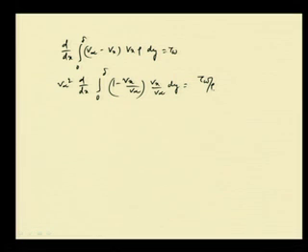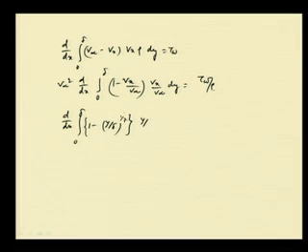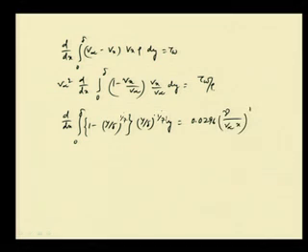Now we put that expression for Vx by V infinity, and we get d dx of the integral from 0 to delta of (1 minus y by delta whole to the power 1 by 7) into (y by delta whole to the power 1 by 7) into dy, and that equals 0.0296, putting the value of tau w, nu by V infinity x whole to the power 1 by 5, and from there we do the integration.